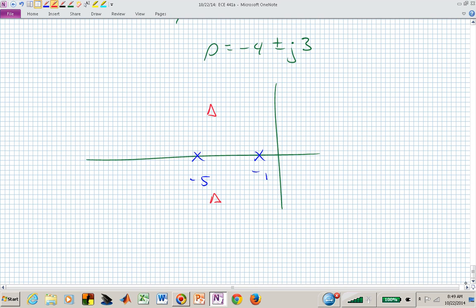Do we have any overshoot in our response? Getting ready for the exam. Very much overshoot. Now look at figure 5.8. Do you remember the angle or the zeta value for a 5% overshoot? Zeta of 0.7, right? What's the inverse cosine of 0.7? 45. Is this angle bigger or smaller than 45? So is our overshoot bigger or less than 5%?